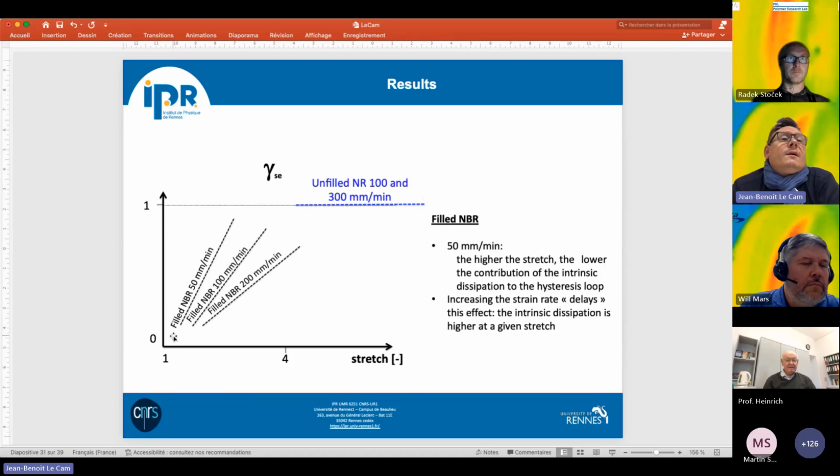Okay, you have here the energy response of natural rubber, and you remember that we saw that there is no real effect of the loading strain rate. Okay, and yes, of course we had to investigate several orders of magnitude of the strain rate, but just from these strain rates, you can see that there was no effect on the mechanical response, but there is an effect on how the material uses the energy brought mechanically to deform. Okay, meaning that for the lowest strain rate, the material stores more energy, at a given stretch for instance, than for the highest strain rate.